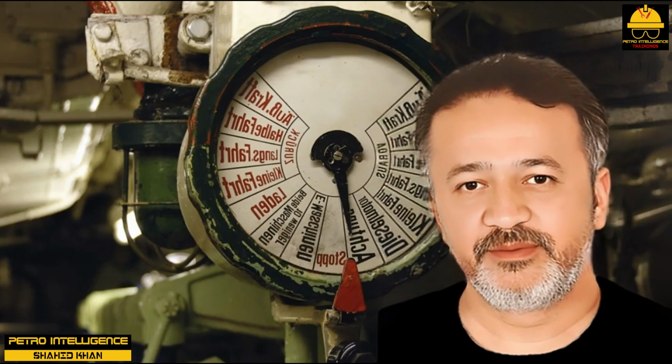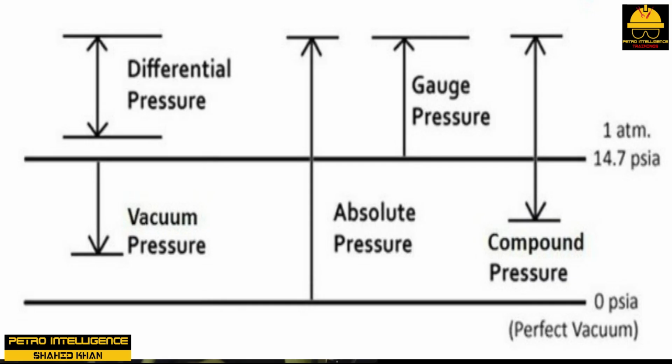Pressure gauges. There are three commonly used pressure scales in the manufacturing environment: gauge, absolute, and vacuum. The most commonly used pressure scale is the gauge scale, on which values are expressed in pounds per square inch gauge, PSIG. The gauge scale starts with atmospheric pressure, 14.7 psi, as 0 and moves up the pressure scale. The absolute pressure scale starts with a perfect vacuum as 0. Values are expressed in pounds per square inch absolute, PSIA. The absolute scale takes into account atmospheric pressure.